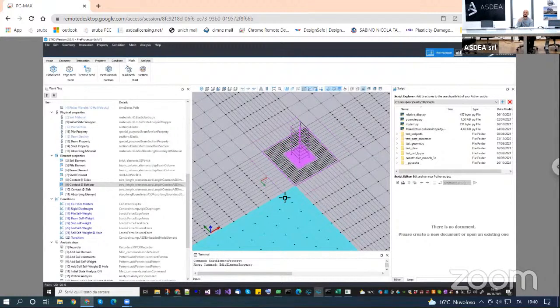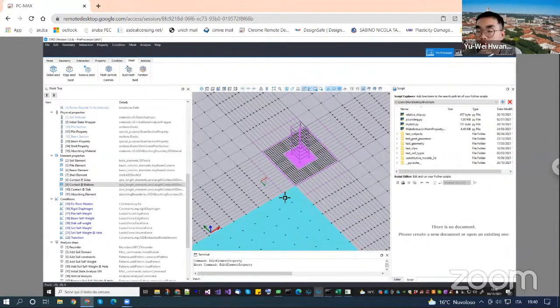Because, for example, imagine the G modulus becomes negative just because it is the derivative of my stress-strain law going down. I will assign a negative shear modulus to the absorbing boundaries that instead are working in a linear case. So a negative stiffness means I have a positive displacement and a negative force, and so it doesn't make sense in that case.